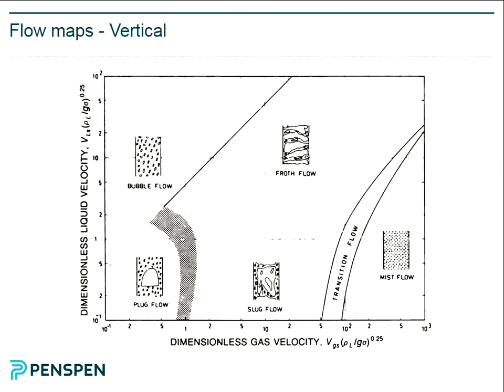And typically these are used for black oils, which is the description of the product. Now for gas condensates, there are no black oil models, so you have to use a compositional model. The other term for a compositional model is an equation of state. So you plug in all the different compositions, and there are tables of coefficients within the calculation method. These are various researchers that have come up with what we call equations of state. They predict fluid properties from the composition at temperatures and pressures.